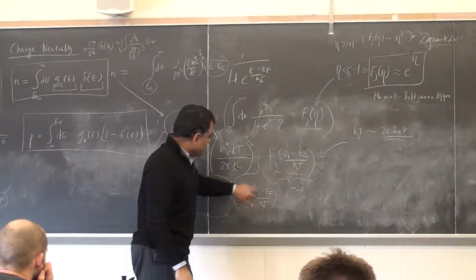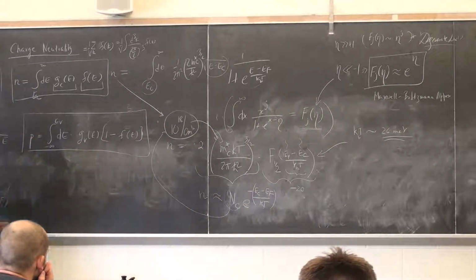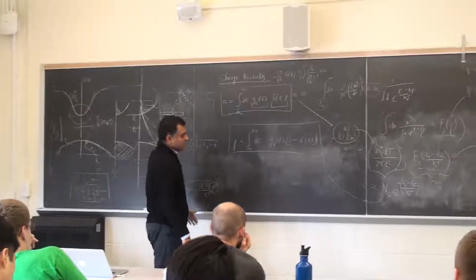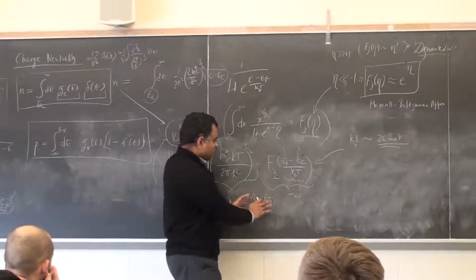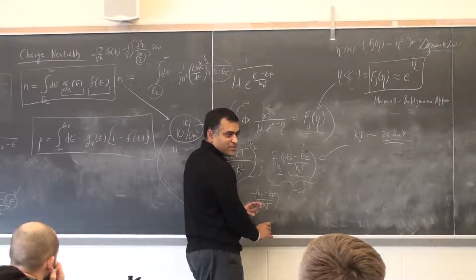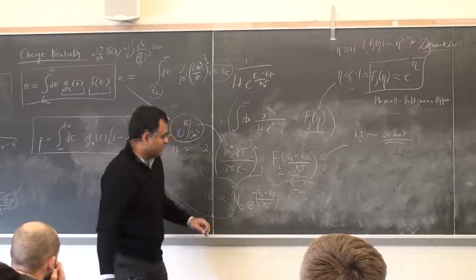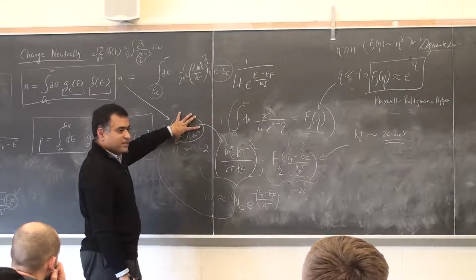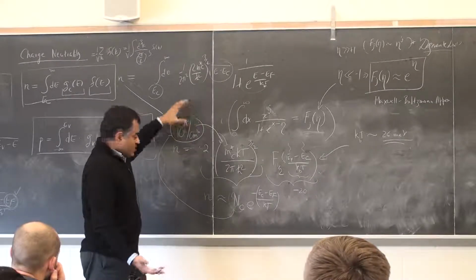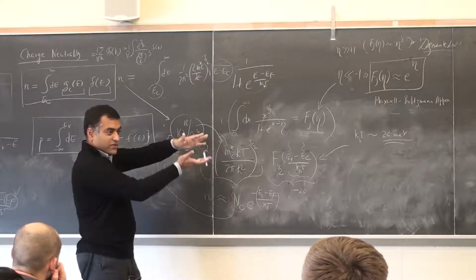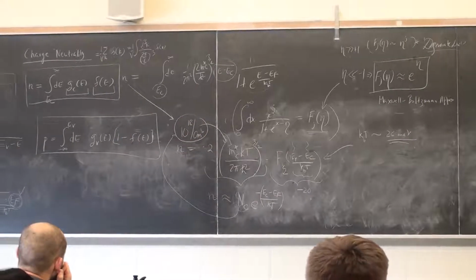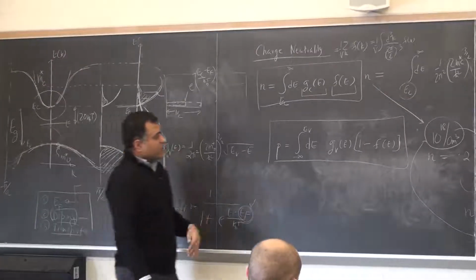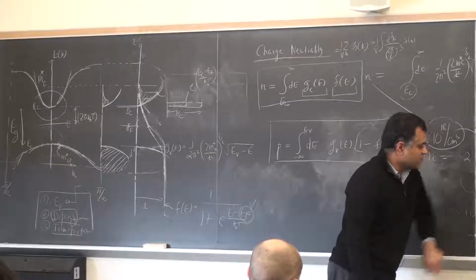And based on that, if I tell you where the Fermi level is, you should immediately be able to tell me how many electrons are there in the band, right? So let's say EC is equal to EF. I know that kind of violates this approximation, but let's forget about it for a second. What if EC is equal to EF? How many electrons are there if the NC is this? It's exactly 10 to the power 18 per centimeter cube electrons. So if your Fermi level goes up right there, that's the order of electron density you're going to get, very close to the conduction band. If it goes far away, it goes down exponentially, and you can see the exponential decay.